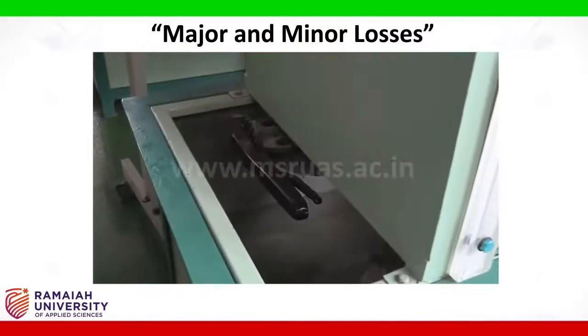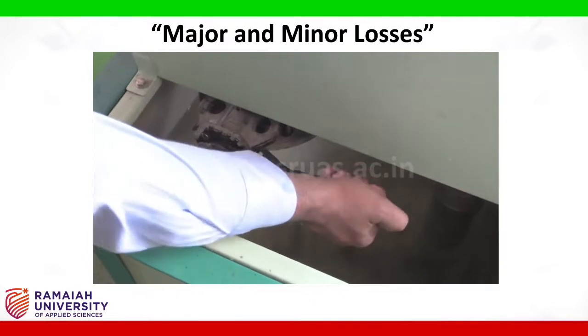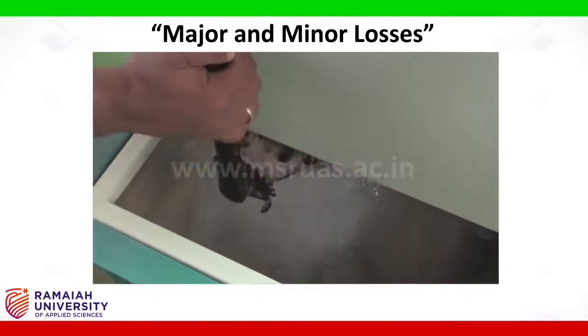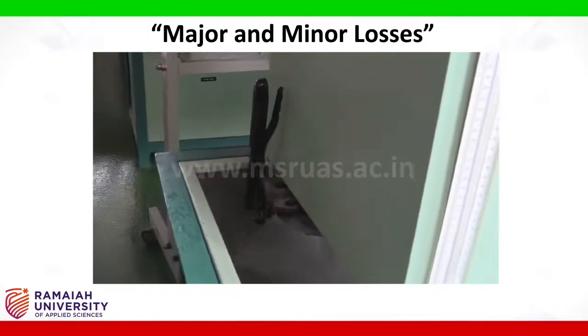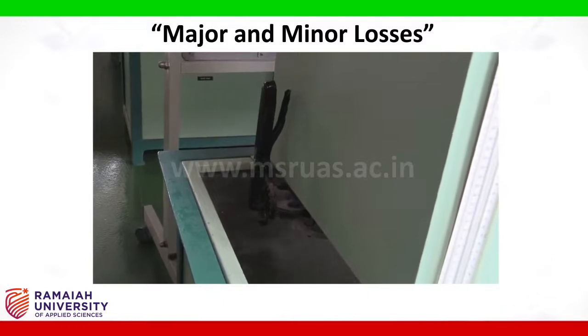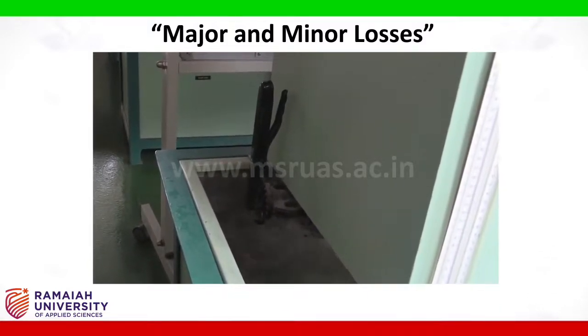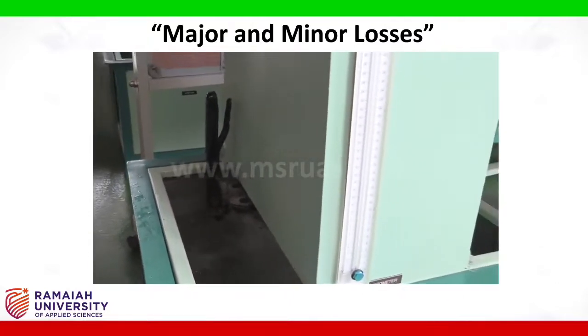Once the time is noted, we should open the butterfly valve back. This process can be repeated a number of times in order to get a consistent value of the time taken to collect the water in the collecting tank.